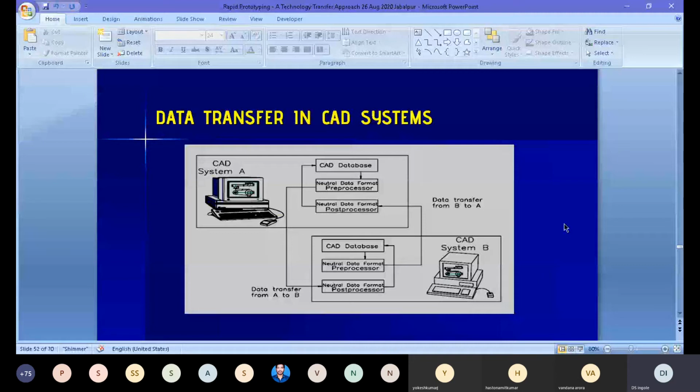There is no intervention of a human being to improve the curvature, improve the dimensions and all that. And that is sent to pre-processing software. Again, that is an automated process, that is, tool path generation is automated. You can only set what the accuracy level should be, and what the build orientation should be, whether you want to fabricate it horizontally, vertically, or by offering some tilting angle.